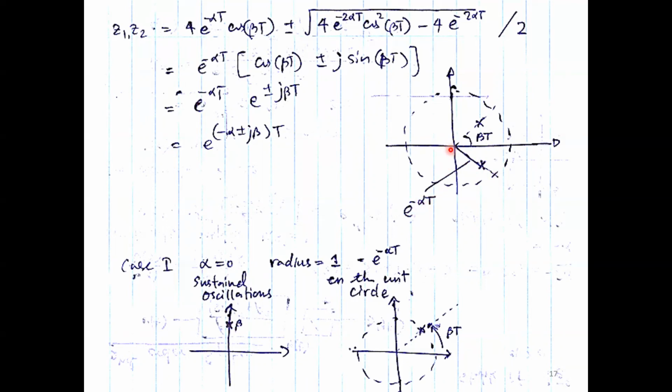So which is 1. Then your pole is actually right on the unit circle, which means it will take infinitely long time to decay. It will not decay actually. So the response will oscillate forever. Because there's this angle between samples and it will sustain forever, these oscillations.